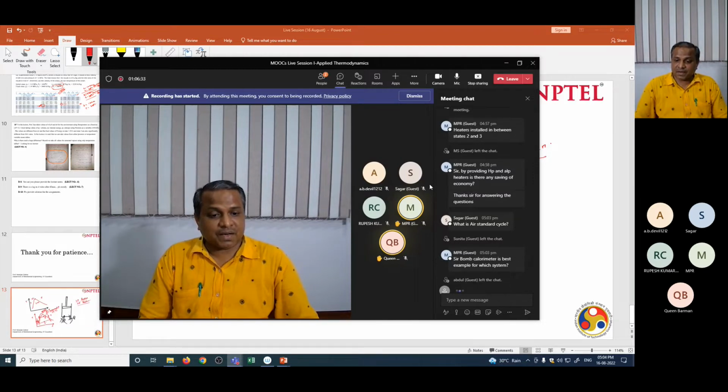So for the thermodynamic analysis, we say that as if air is being used as a working fluid. So this is the first assumption. We say air is the working fluid. Now, from the thermodynamic viewpoint, when you say Otto cycle or diesel cycle, the heat from the fuel is replaced with just a heat addition process. So with those assumptions, the Otto cycle or diesel cycle are modeled.